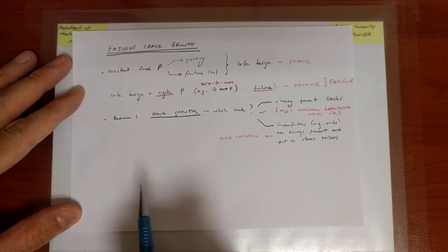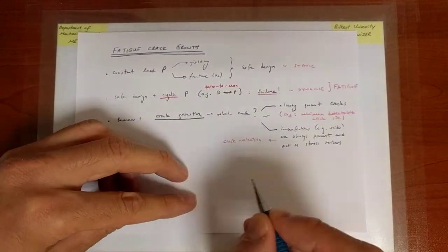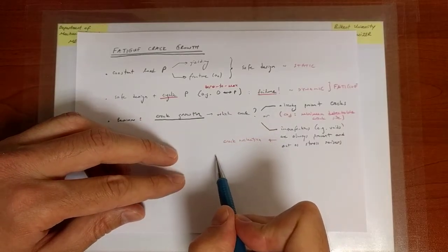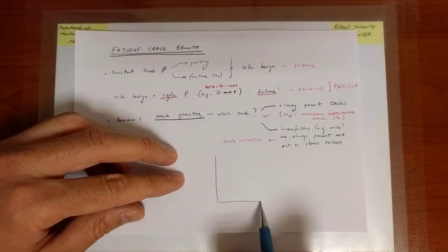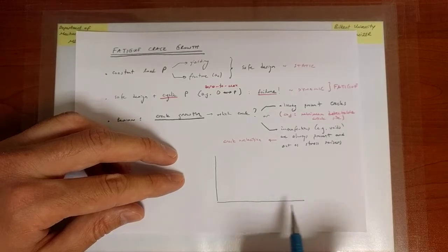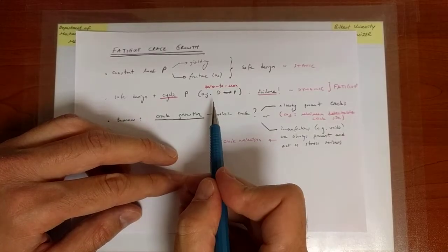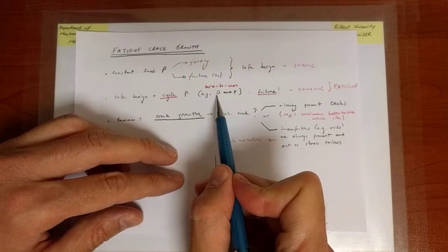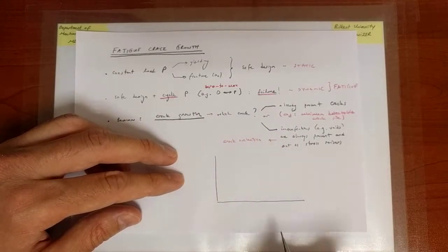Right, now let's try to slowly put into equations what it is that we are trying to do, and in the meantime, we're going to start introducing some terminology. The first thing we are saying is that our load is not a constant. The load actually varies over time. The way we can quantify time is either time itself, or because we're talking about cyclic loading, we can count the number of cycles. So in other words, I load, that's 1, 0 to P back to 0, that's 2, 0 to P back to 0, that's 3, 4, etc. Each one of those is a cycle.